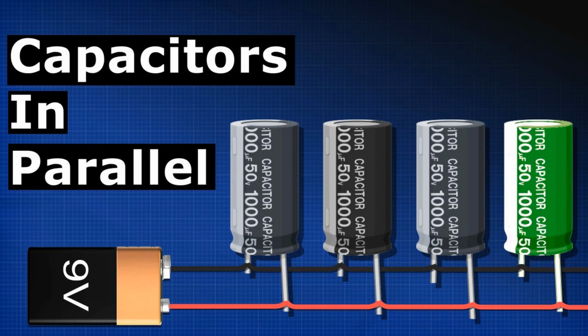Applications of capacitors in voltage regulation. Power supply filtering. Description: capacitors smooth out fluctuations and reduce ripple in the output of power supplies. Example: in a switching power supply, capacitors filter out the high-frequency noise generated by the switching process, providing a stable DC voltage to the load.